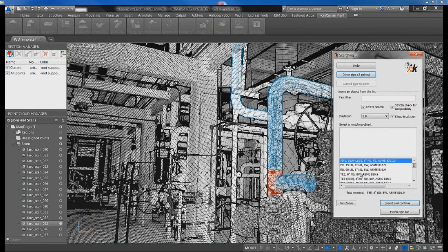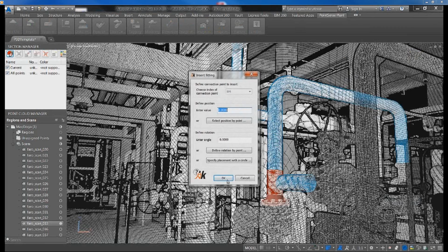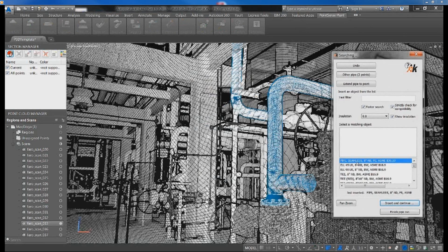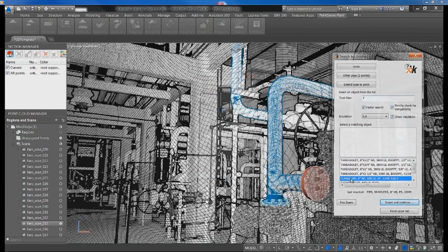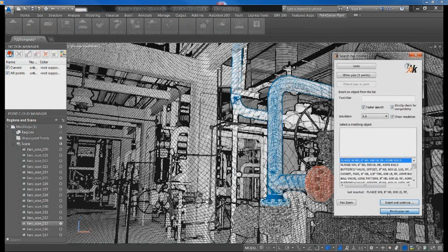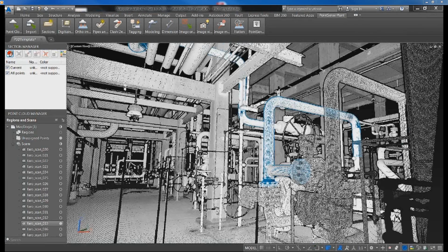Now, all we need to do from this point on is go ahead and put our flanges on the end, and then after this, we'll have the line ready to do apply constraints. Now, if you remember from the previous slides, the point of apply constraints is to fix all of the micro errors in the center lines or in the fittings. And through time and through thermal expansion, through vibration, wind, just freezing and heating and all that stuff, your fittings are going to start to warp.